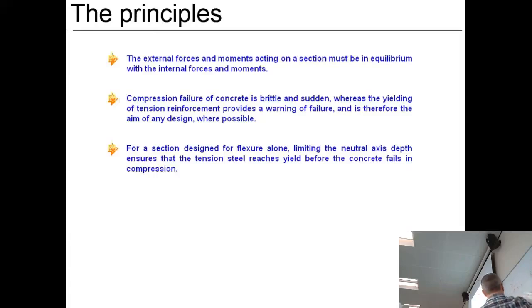But when we come to do the design, you'll find that the concrete below the neutral axis isn't actually considered in the design. Normally, because when a beam bends, you end up getting a lot of cracks within the bottom half, so they don't rely upon that. And all of the tension's held by the bars. Concrete's got about 10% tension, but again, it's not considered in the design.